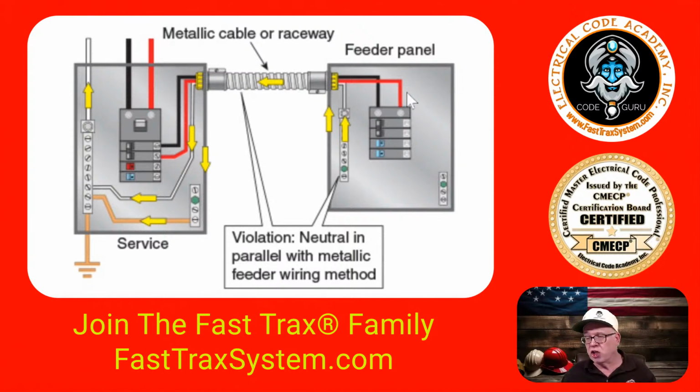Now, could this be liquid tight flexible metal conduit and this be a 60 amp remote panel? Maybe. And if that's the case, if you meet all the length limitations and follow those rules, then maybe you can get away with that. But other than that, you're going to be very limited in the application.